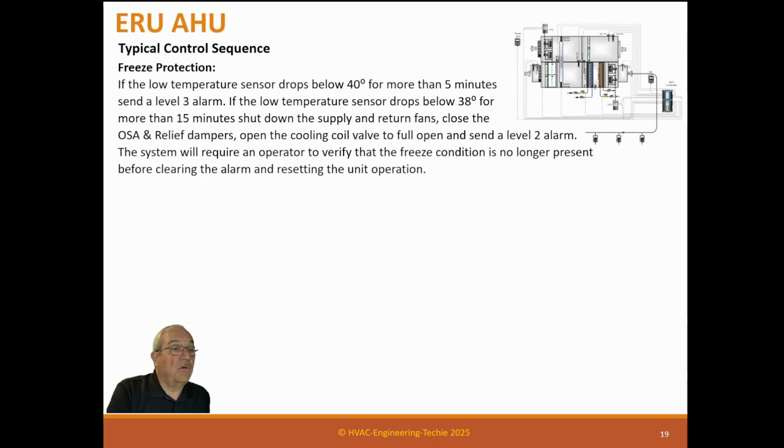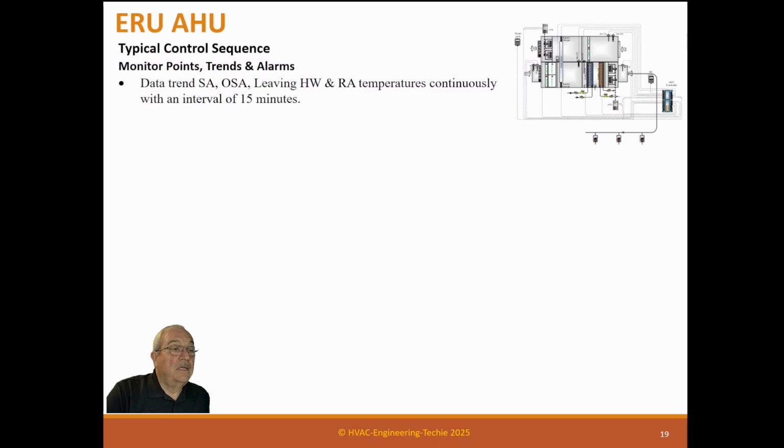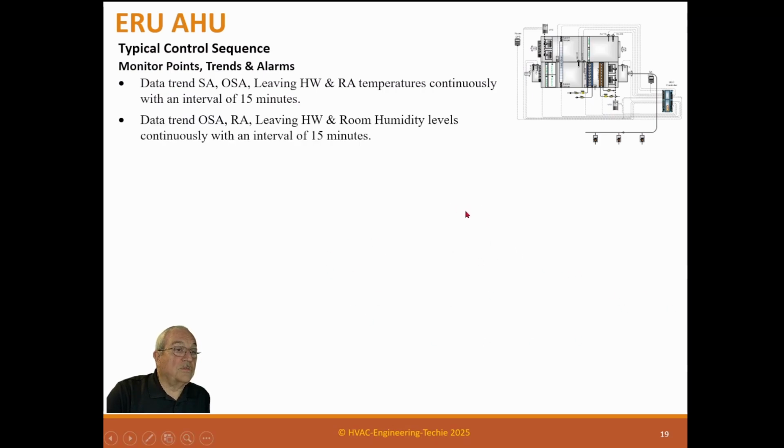The system will require an operator to verify that the freeze condition is no longer present before clearing the alarm and resetting the unit operation. Monitoring points. Data trend supply air, outside air, leaving hot water, and return air temperatures continuously with an interval of 15 minutes. And these are just status points to see what's going on.